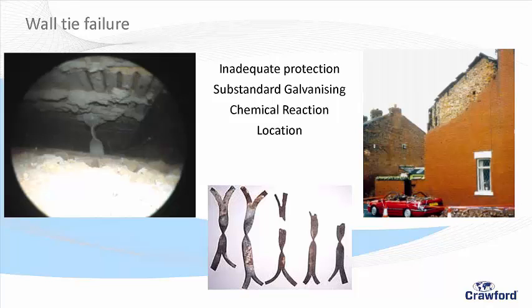Yeah? And cavity wall construction is good because it's cheaper than a solid masonry construction, introduces a bit of thermal performance to it, sound performance, breaks the outer wall to the inner wall, stops moisture transmitting. And if you're using nice fancy brickwork, you only have to use it on the facing brick. And on the inner face, you can use cheaper blockwork, which is better performing. But if you've got two walls, you need to join them together. You need to have a wall tie to do that.